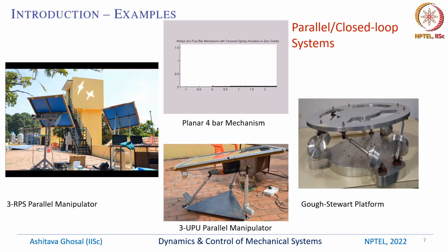One of them is actually a serial device. There is one motor here and another motor here, one after another. If I rotate these 2 motors in a particular way, I can track the motion of the sun, and then the incident beam will be reflected onto this receiver. I can do the same thing with the parallel robot or parallel system. In a parallel robot, we have these 3 actuators or 3 joints, and they form loops.